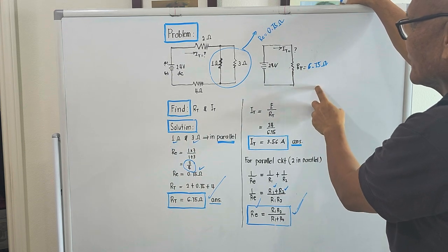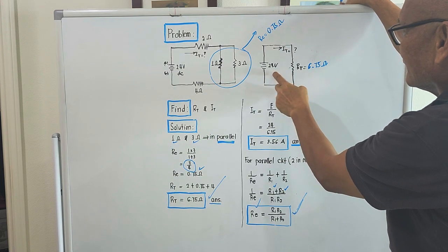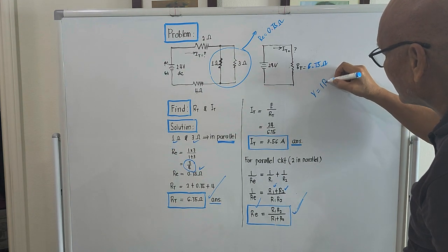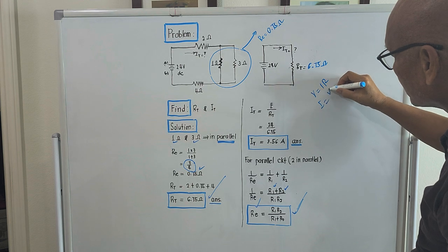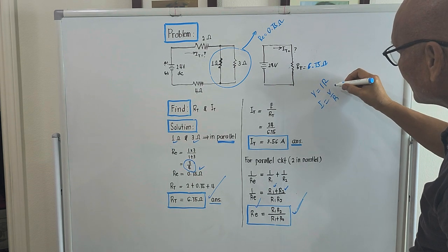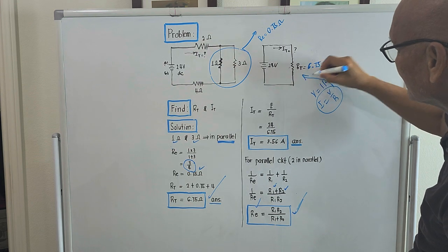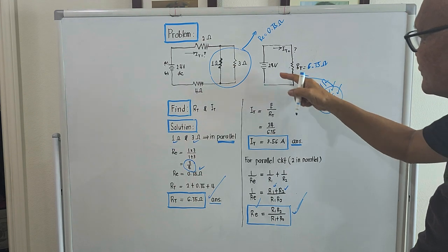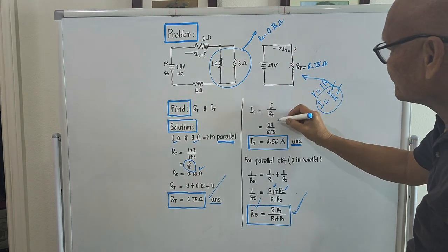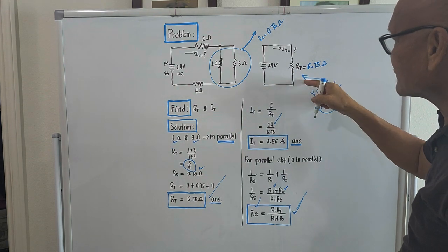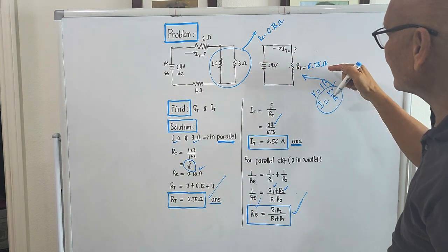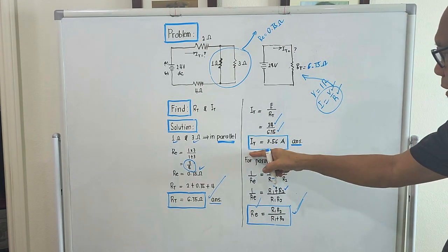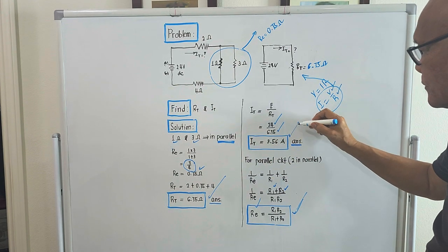So to compute for the total current, it will simply be this voltage here divided by this total resistance, by using the formula voltage equals IR, and we will compute for I, it should be voltage over R. Okay, so applying this equation back here, we are given the voltage, we are given the resistance. The total applied voltage is actually 24, and the total resistance now, as per our computation, is 6.75, right? It is over 6.75, and the total current will be 3.56 amperes. That's it.